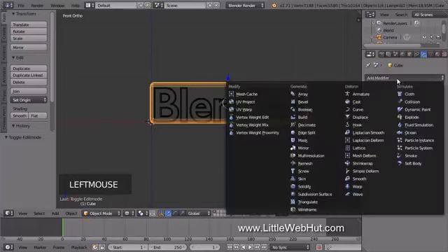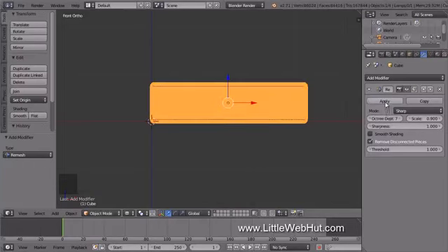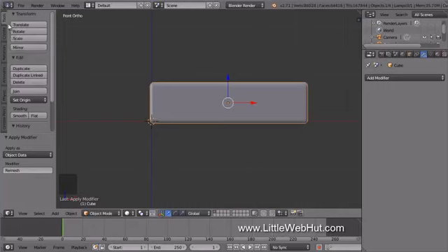So click the Add Modifier button and select Remesh. We want a lot of detail, so set the Octree depth to 7. Then click Apply. Now click the Viewport Shading menu and select Solid. To add extra smoothing, click the Tools tab and then click the Smooth button.